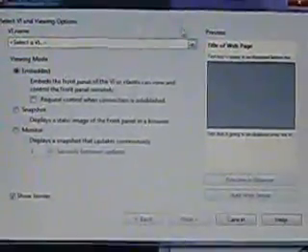For that, first we have to go to whatever VI we want to send to the doctor, go to the VI's front panel. In that we have to go to the Tools menu and select the Web Publishing Tool. In that we will get this type of dialog box, and then we have to select the VI we want to send to the doctor.